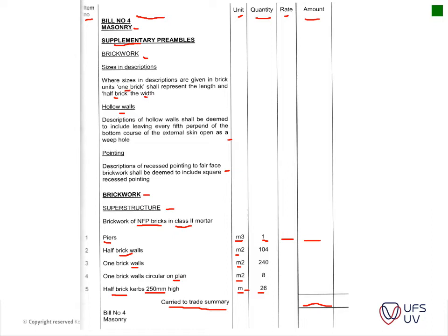Obviously there are still a lot of items that are not listed here. For instance, your reinforcing is not measured here. If there's face brickwork, it's measured separately, as is brickwork in foundations. If there's a coating that has to be put on to the brickwork, also. Then your bills will usually go over a couple of pages. Each page is added up here,